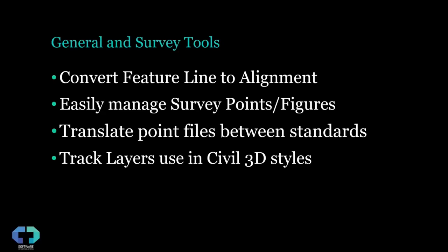If you have a need for working with different point files and specifically different point coding standards, oftentimes surveyors in the field are having to code in different fields or code sets. We can ensure that they work with one code set, and then you can make a translation before you import that into Civil 3D. So maybe you're converting from one numeric standard to an alpha standard, or from an alpha to a different alpha standard, depending on the coding standards you have to work on.